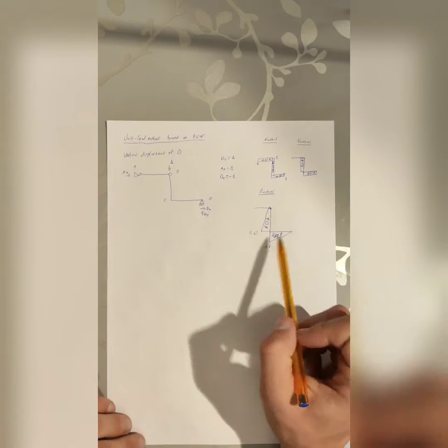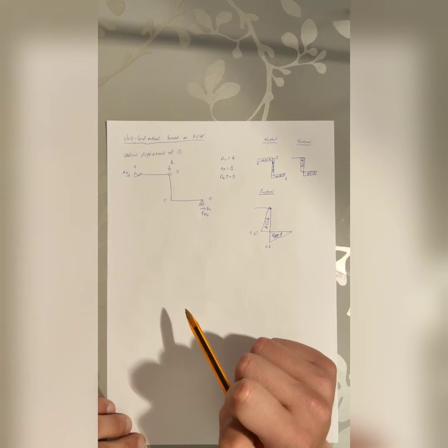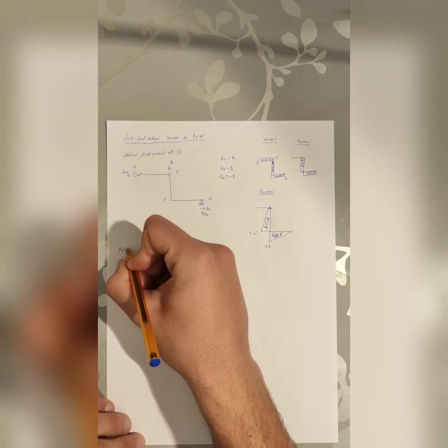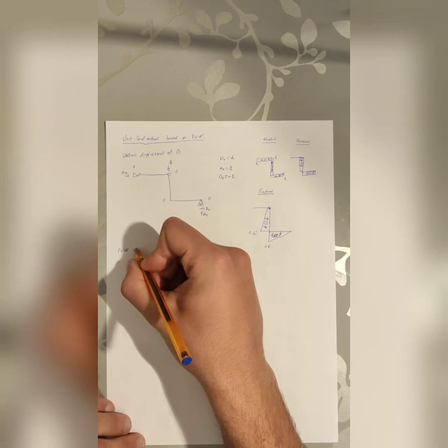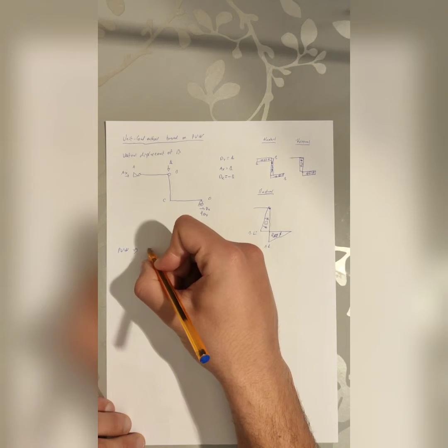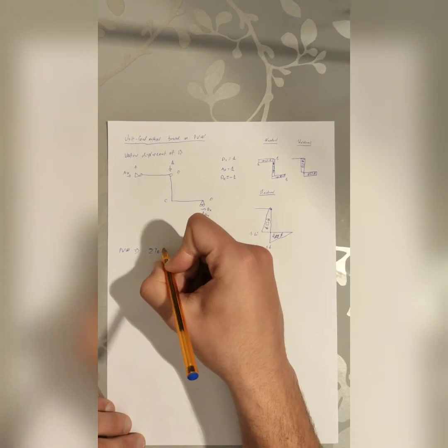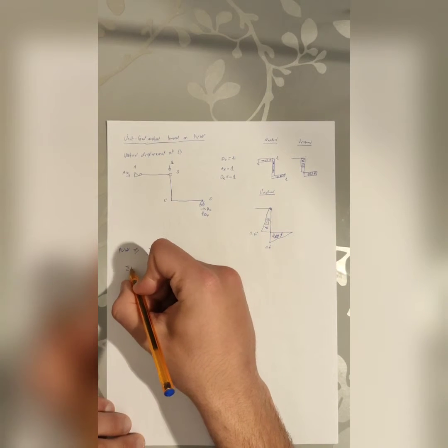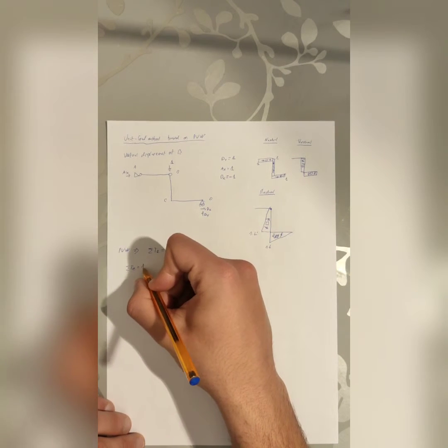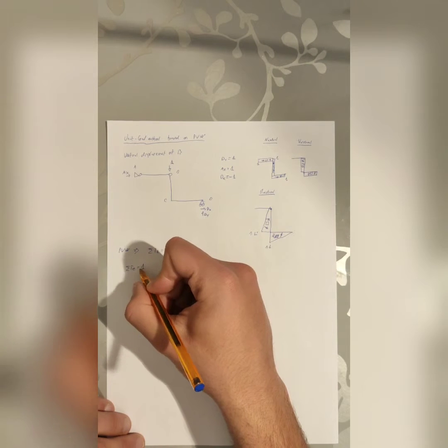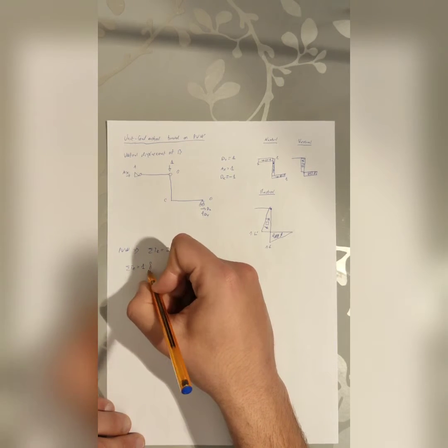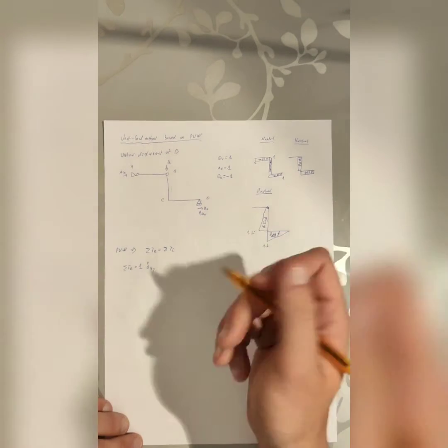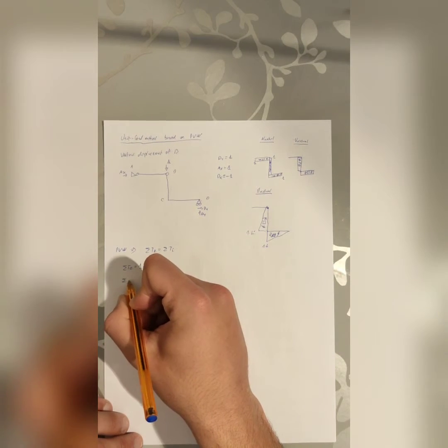Once we have the moment diagram, we can start to calculate the displacement. As we have said, we use the principle of virtual works, which says that the external work is the same as the internal work. The external work is the product of the forces and the displacement, since the unitary force is 1 and the displacement that we want to calculate is By, the vertical displacement at B.